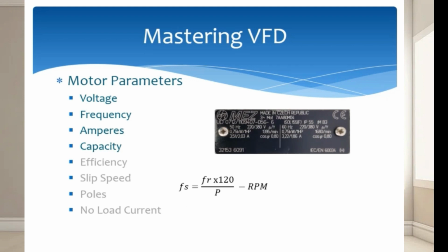I added a motor nameplate and we will get the desired parameters. So we see it's rated 220 or 380 and there are symbols. It's known as star or delta. This is a connection type. So if the motor connections are of delta type, then we will pick the value 220. But in case of star connection, 380 will be the right voltage value.